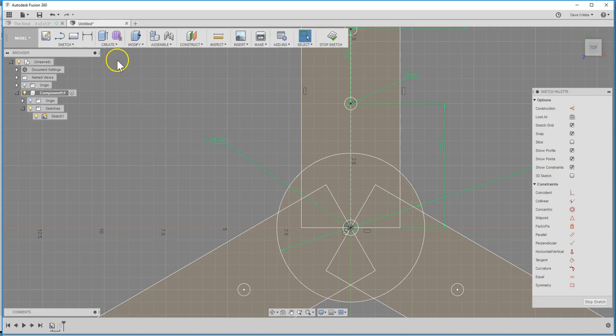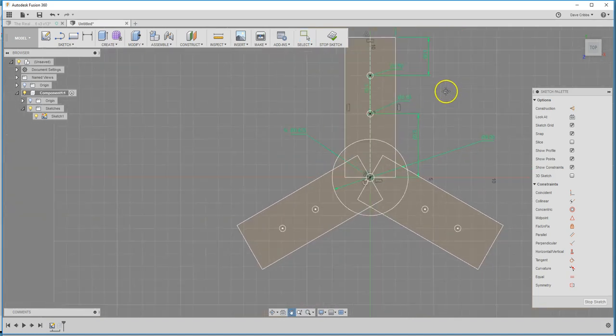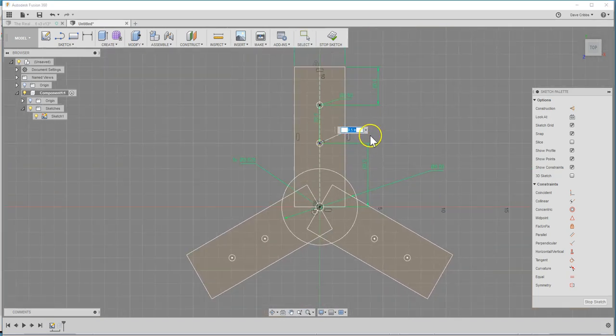This depends upon what I entered into the parameter table. So same thing, I'll come here, double click that, enter D, and that's the diameter of the holes on the flange. So you've got to make your variables descriptive enough that you can understand what you wrote.